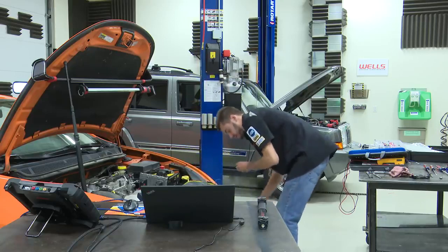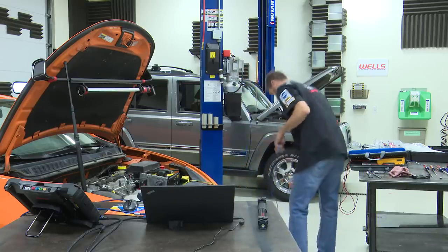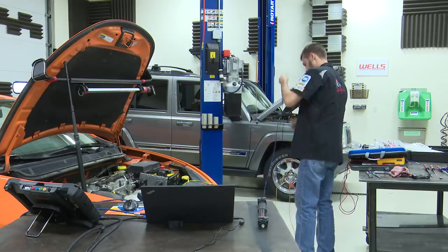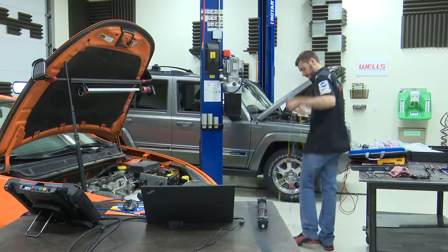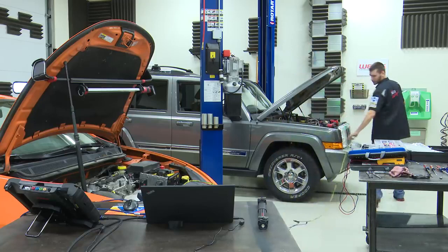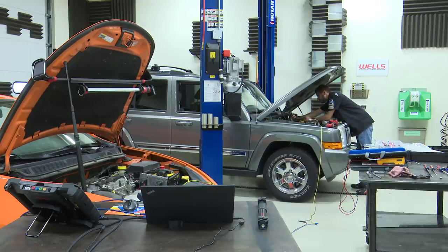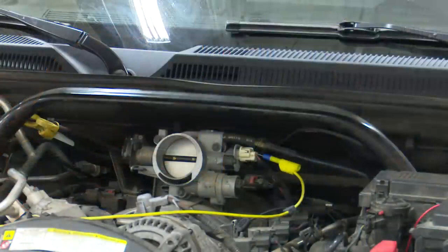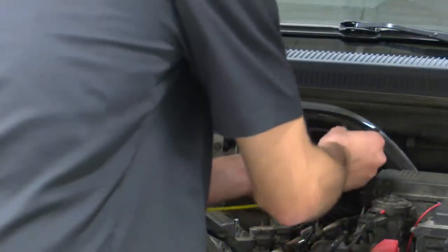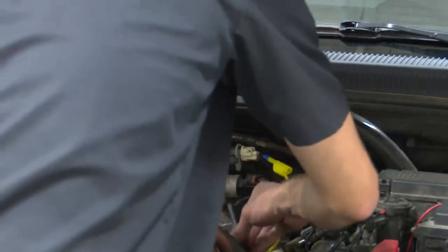But I'm just going to go ahead and grab one channel off of our scope, and I'm just going to piggyback it onto these other leads and hopefully have enough to reach all the way over here through 20 feet of cables. Again, don't do this if you're in the shop. It might mess with your signal strength, or I mean, you're just going through more resistance, right? The longer the wire, the more resistance. And let's find a ground. Alternator bolt right here looks good.